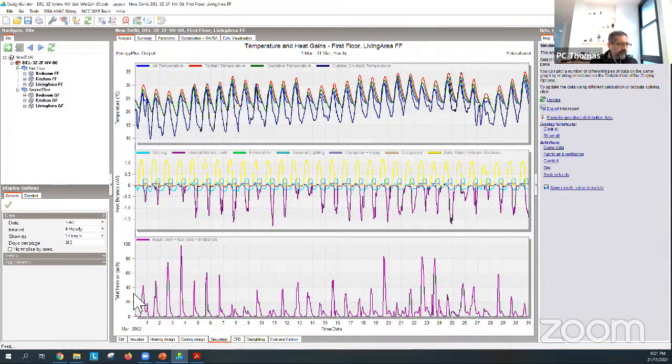And also if you look at these numbers, you can see these numbers are very much different from when the air conditioning happens. When you're doing air conditioning, you might be lucky to get 2 or 3 air changes per hour. You can see here that you're almost getting 100 air changes per hour. So there's a lot of wind suddenly at the right direction for a short amount of time. You get a huge amount of airflow. Typically, it might be much less, but you're getting these bursts of big ventilation happening through the building.